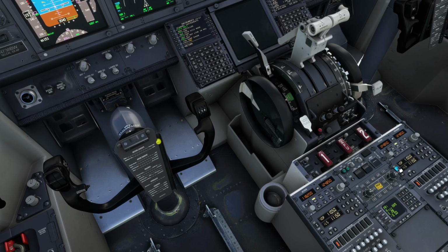This is a reset that I'm doing on the system because all the options that you choose here only take effect the next time you select your approach when it's in reference to auto Alpha 3 mode. So that's why I selected what I want. I want to show you the auto Alpha 3 mode. That's why I took it to yes, and then I reset the ILS here for the system to understand that the next approach we want it to be working.